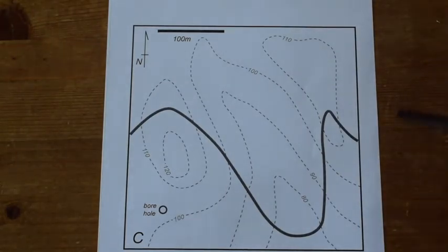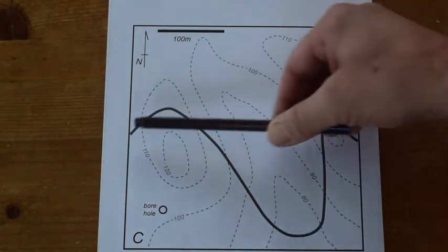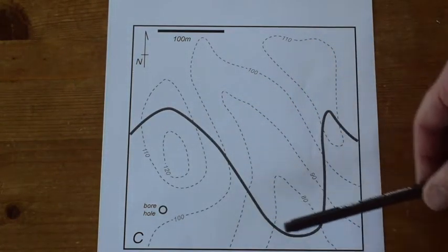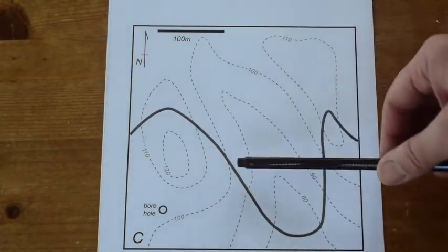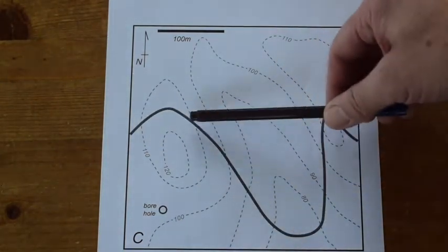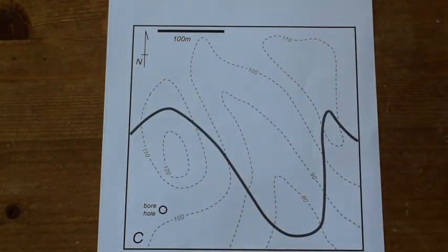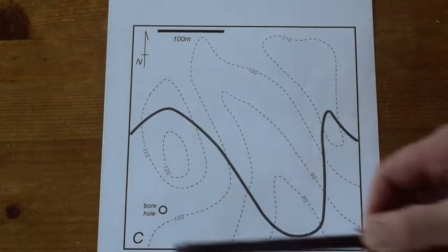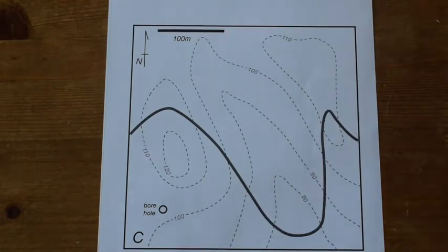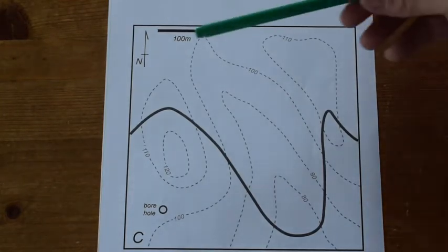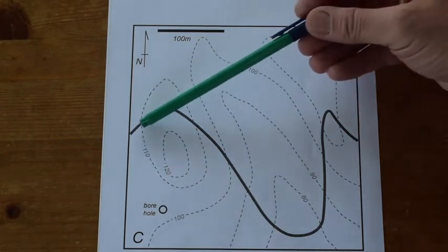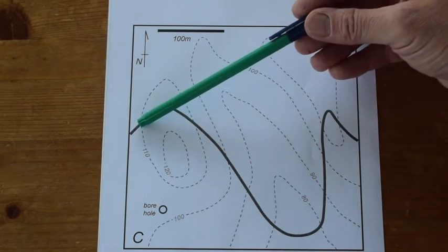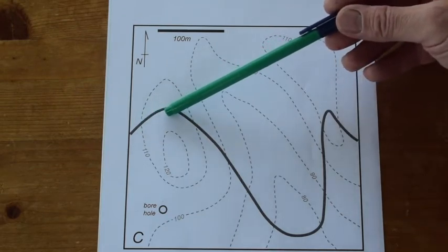And what we're going to do is draw structure contours on this feature running through here, this geological layer, using the map pattern, in other words, how this layer interacts with the topography. Our mission is to estimate the depth to this layer in this borehole. So let's walk along this boundary and find the intercepts of it with some topographic contours. We're going to look for the contour elevation that intersects this horizon the most times.